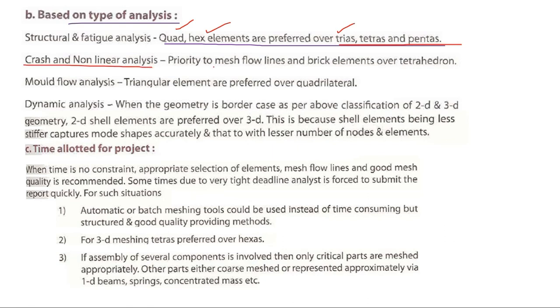Crash and nonlinear analysis: priority to mesh flow lines, brick elements over tetrahedron. This tetrahedron, brick, all these things we can see when we go for the type of elements we are studying. And mold flow analysis and all, we are not doing it as structural, it's mainly for mechanical.